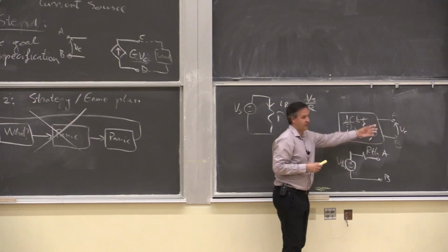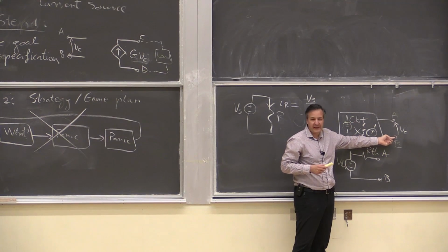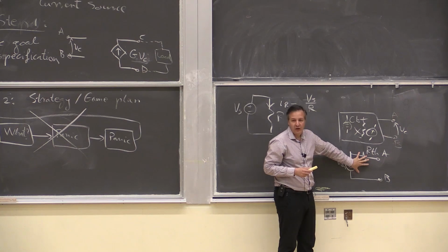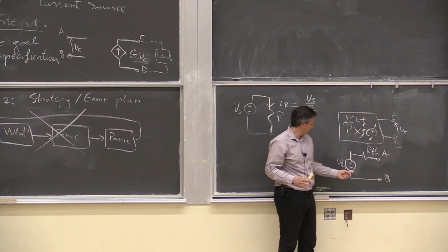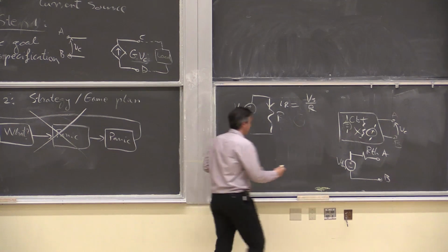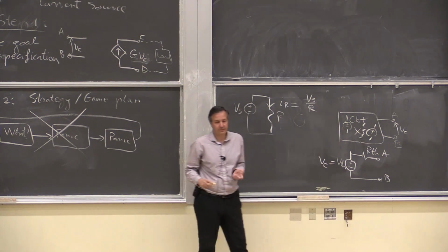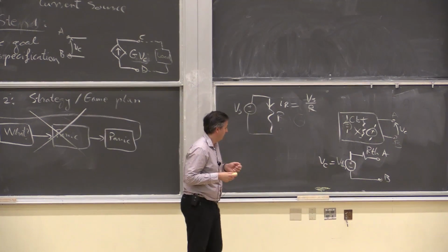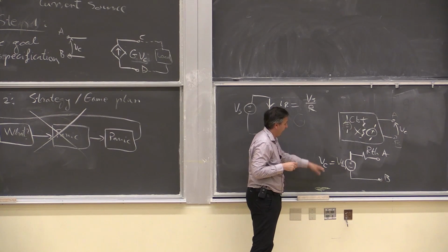What is the value of the Thevenin source? If I tell you there's a whole bunch of junk in here and VC is the voltage between terminals A and B, and I want this thing to exactly give me that, voltage VC between terminals A and B. What is VThevenin? VC. Right. Okay.